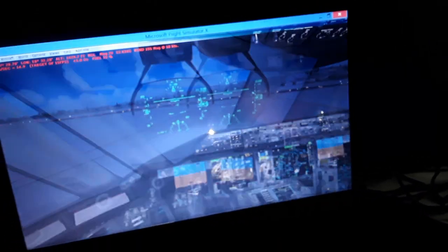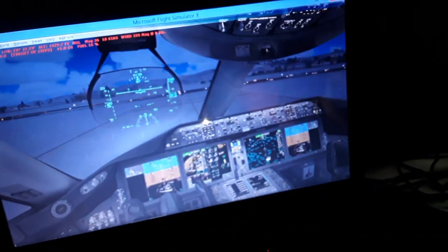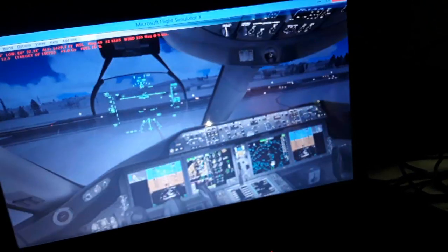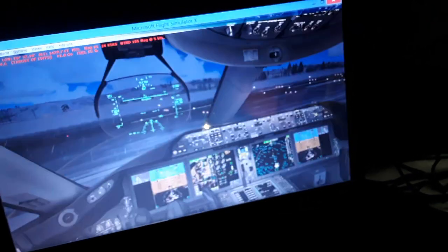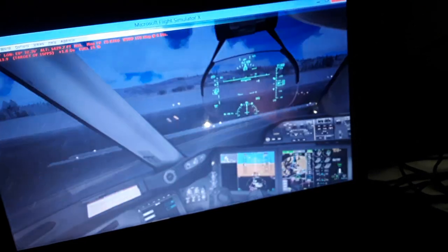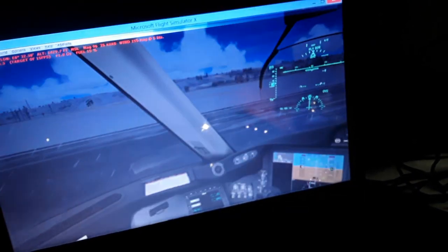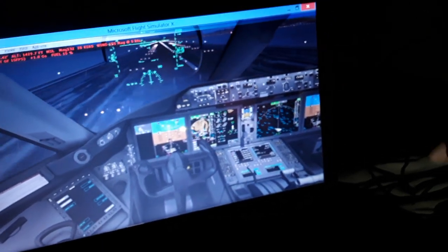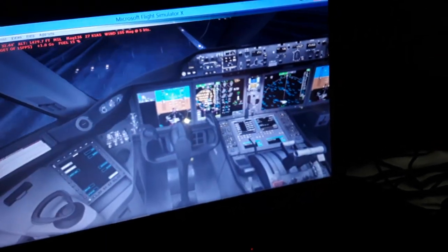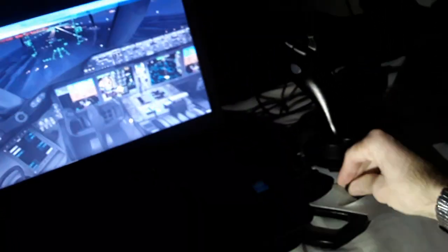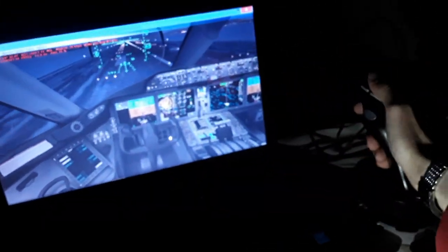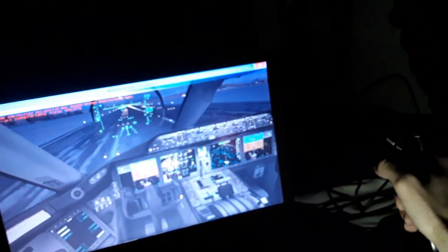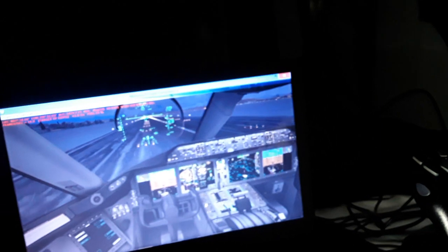So this is the runway, it is empty. We take the runway clearance from the air traffic control and use the nose wheel steering here. So use nose wheel steering, tiller like this for alignment. So we use takeoff power like this, full takeoff power. So we're taking off.